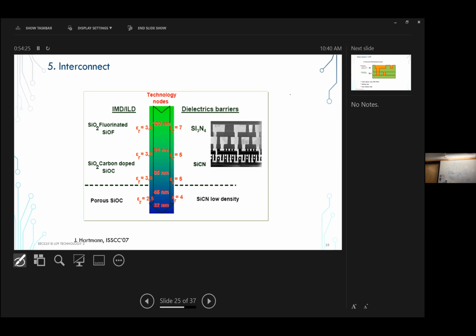For gate materials, you want it to be higher. For isolation, we want less capacitance, and we want to drive that epsilon r down to 1, essentially what looks like an air gap between them. There have been quite a few changes, but I've not seen design rule implications we need to worry about.